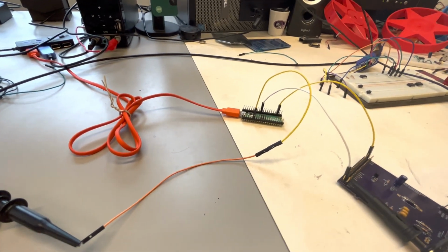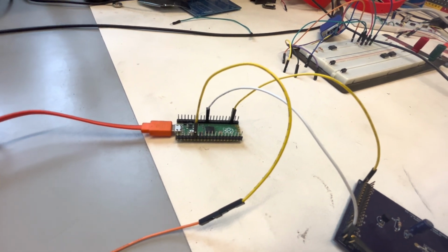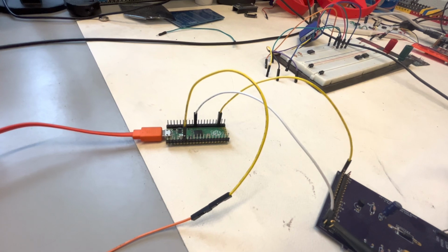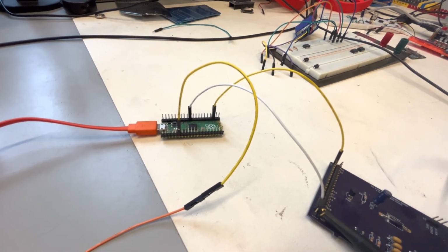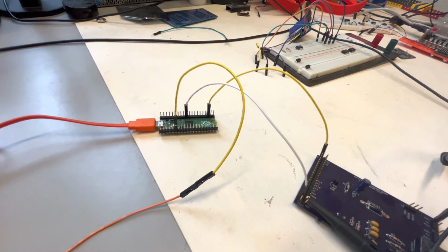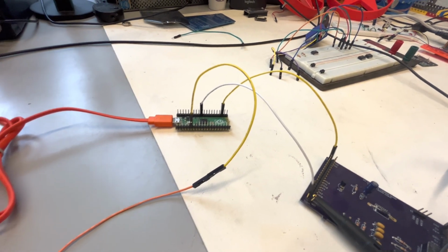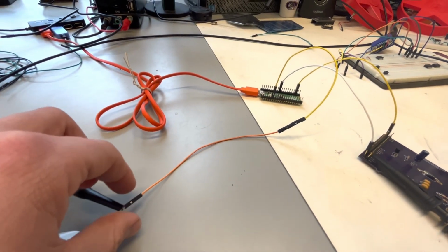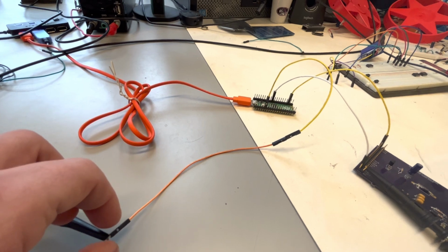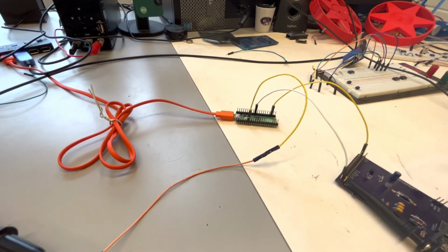As I speak, the ADC is going to automatically sample my voice coming through the microphone and truncate those samples to 8 bits and put it into the ADC FIFO. And then a DMA channel is going to automatically move those ADC samples over to the capture compare register for this PWM channel, so that as I speak, the PWM channel's duty cycle will adjust automatically to approximate the analog voltage that it sees coming out of the microphone.